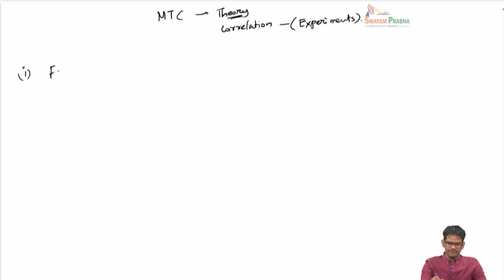So for the liquid falling film case, this coefficient KL is given as something like 3.41 DAB by delta. This is very simple. You can see this L here means it is a liquid phase mass transfer.